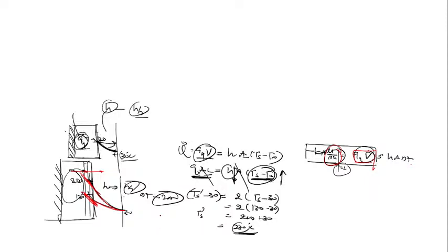And if the gradient is the same, then obviously here I got this type of profile, and here I got this, and obviously the maximum temperature will increase. T maximum will increase in the material, and everywhere the gradient will be as it is, but only the temperature has been increased. So the slope in the material at any given point, dT upon dx, will remain the same, but the profile is only shifted up, because the maximum temperature will increase.